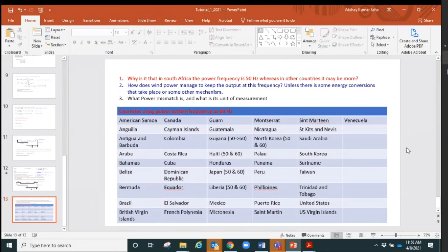But again, we'll also have to consider other things. When I'm saying I'm increasing the excitation current of the rotor field winding, I need to know the maximum rotor field current that the rotor can carry, I don't want to damage that. When I increase the rotor excitation current, it reflects on the reactive power and the generator terminal voltage. I want to be at 1 per unit, but the reactive power is also increased. Because of increasing reactive power, the generator stator current will also increase. Then again, I will also need to know what is the maximum stator current allowed for this generator. So there is a limit for that as well.